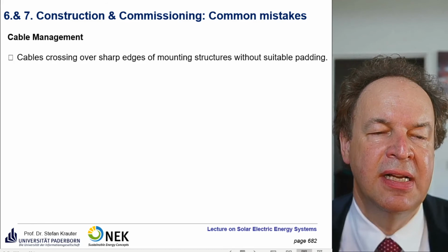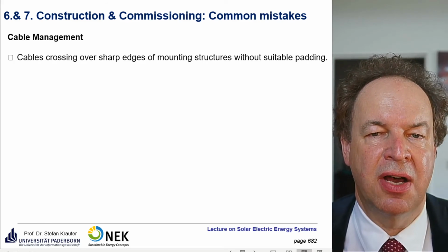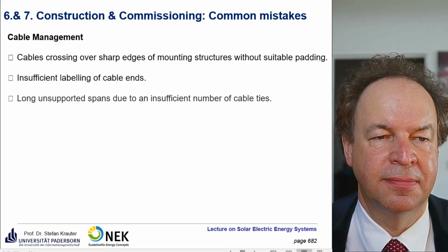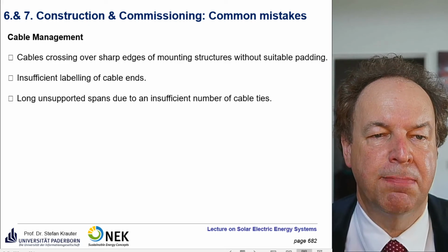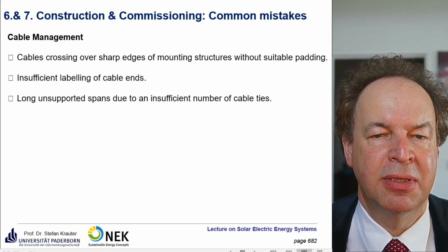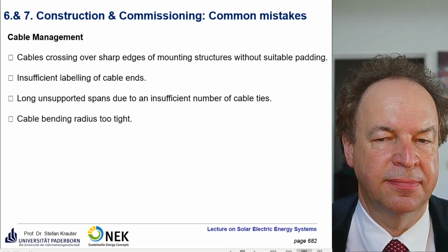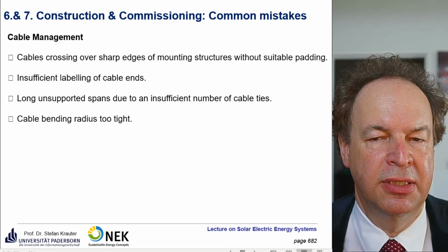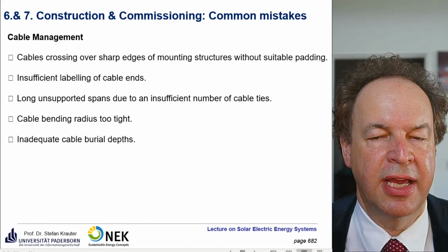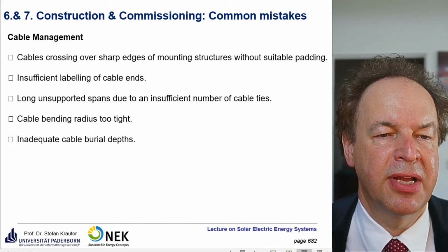Cable management. So cables crossing over sharp edges or mounting structures without suitable padding, insufficient labeling of cable endings, long unsupported spans due to an insufficient number of cable ties, cable bending radius is too tight. This could lead to breakage of the insulation or even of the core of the cable, so the copper and so on. Inadequate cable burial depth,